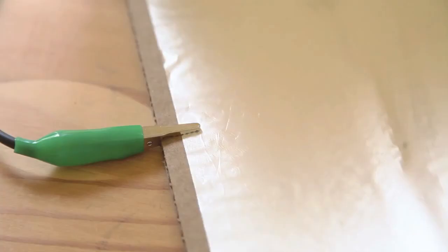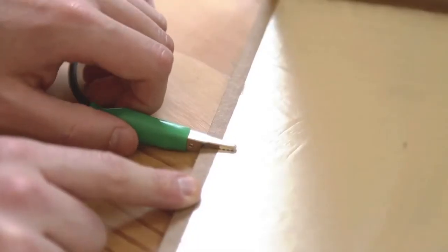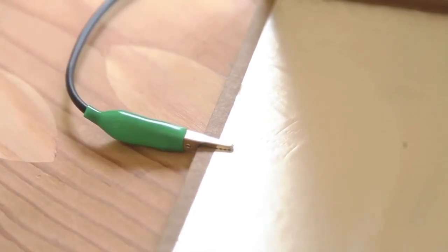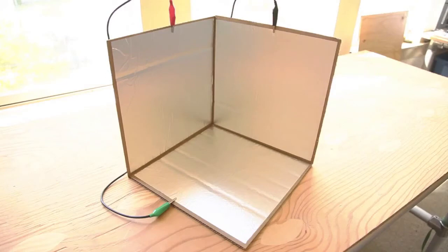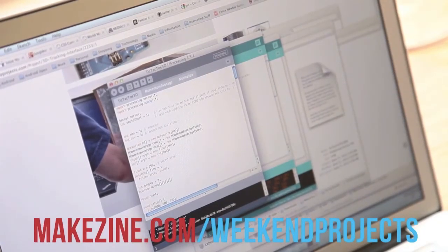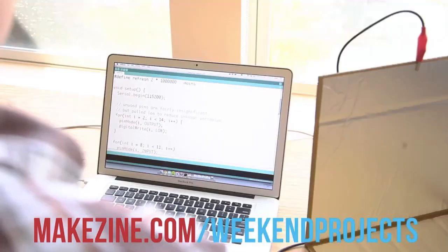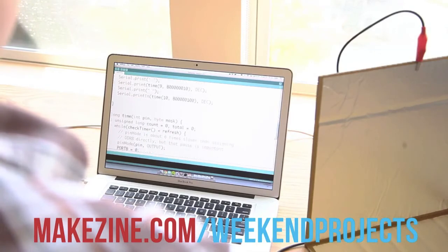The clips should be attached in the following order: pin 8 to the left or X plate, pin 9 to the bottom or Y plate, and pin 10 to the right or Z plate. Make sure that each clip is making good electrical contact with the foil and is only touching one plate. Now the sensor cube is ready, and all you need to do is upload the Arduino sketch. Download the Arduino and processing sketches from the how-to on Make projects. You'll also need the processing and Arduino development environments, which can be downloaded from their respective websites.